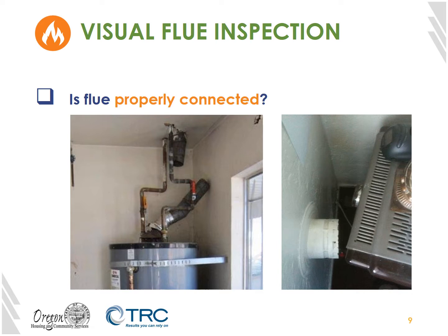On the right-hand photo, we have another combustion appliance that has been disconnected from the flue. So again, if the appliance gets turned on, we're going to have serious problems. And it's really important that we do these inspections before we start turning things on to test them.